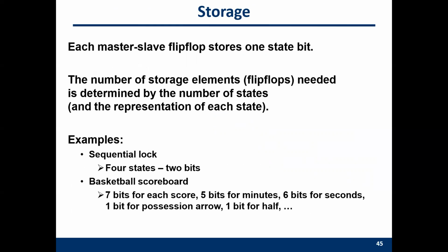So you can see that the D latch is used to record only one state bit. The number of storage elements is actually decided by the number of states. For that lock example, it requires 4 states. For more complex applications, there are actually many more states.